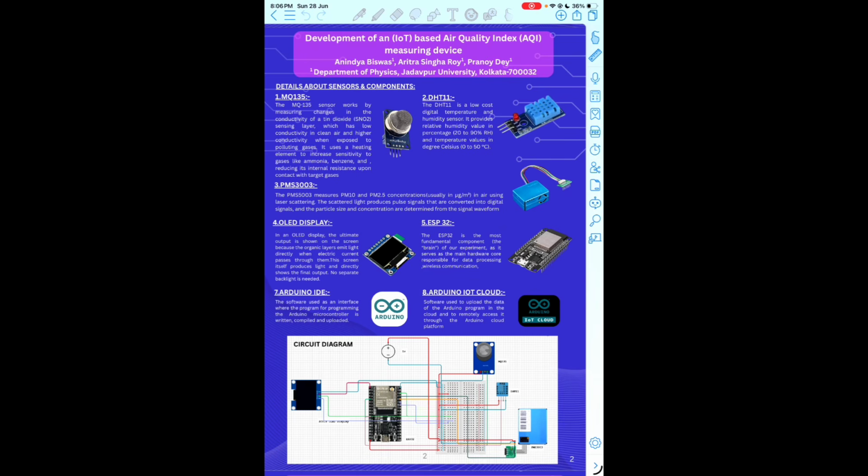This is the PMS3003 sensor, our main AQI sensor. It is a laser-based particulate matter sensor manufactured by Plantower, and inside this sensor a small laser beam shines through the air. When dust particles pass through the laser, they scatter the light, and a photodetector measures the scattered light, and the sensor's internal processor estimates the number and size of the particles. This sensor provides measurements for PM1.0, particles smaller than 1 micrometer, PM2.5, particles smaller than 2.5 micrometer, and PM10, particles smaller than 10 micrometer.